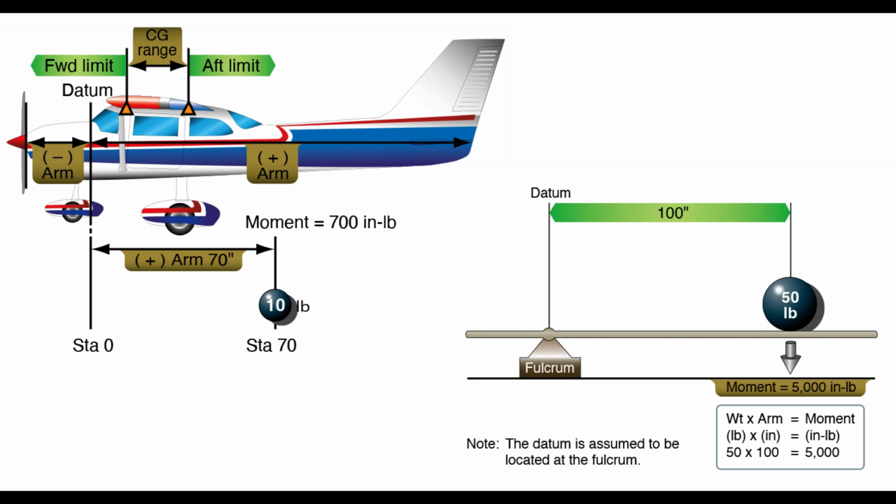If the thrust line is designed to pass horizontally through the CG, it will not cause the aircraft to pitch when power is changed, and there will be no difference in moment due to thrust for a power-on or power-off condition of flight. Although designers have some control over the location of the drag forces, they are not always able to make the resultant drag forces pass through the CG of the aircraft.